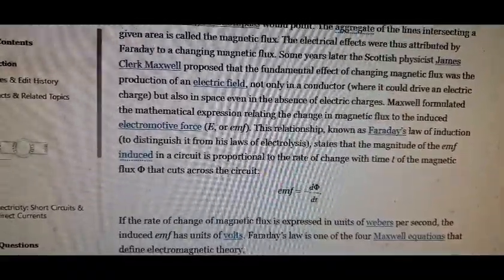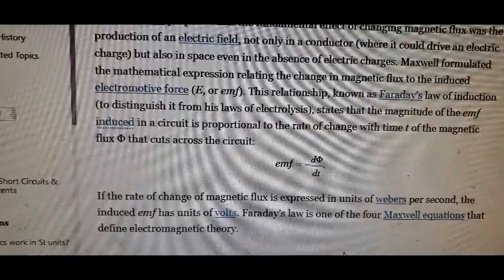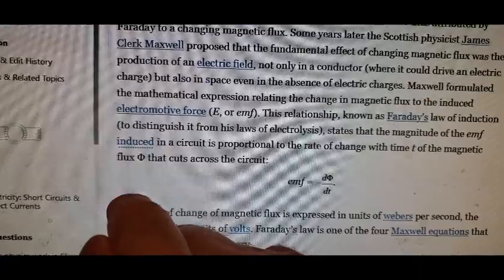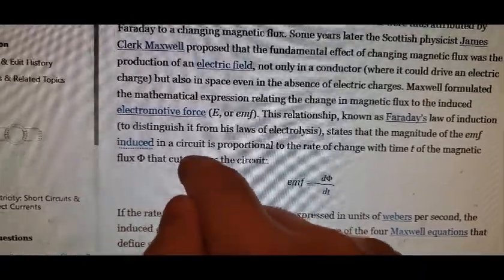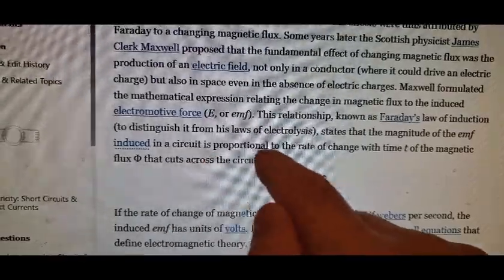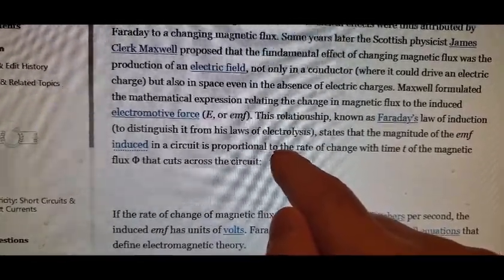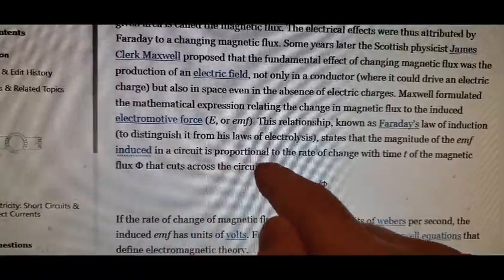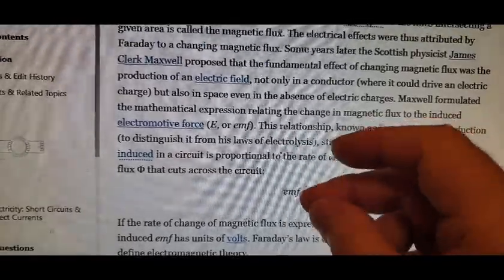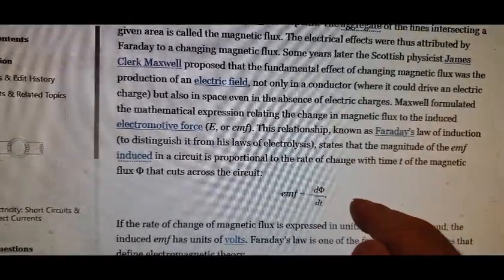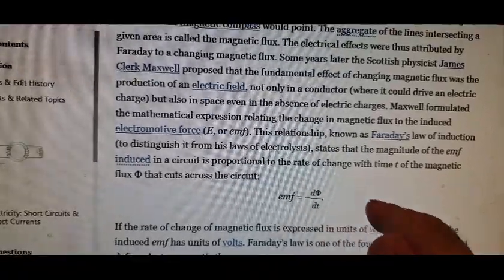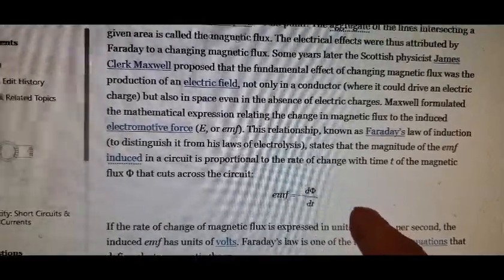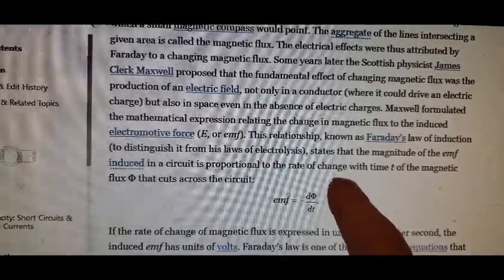So, to use a somewhat silly example, let's suppose that it takes 1 second for the coil to establish its steady state where it's fully saturated with current, and now it's the strongest it's going to be. So if you just ran that coil for 10 minutes and then at the end of 10 minutes shut it off, you would get a good spike there when the magnetic field changed and the coil went back to zero in terms of its amp flow.